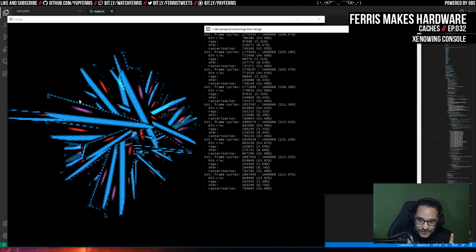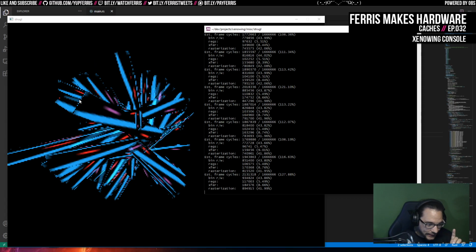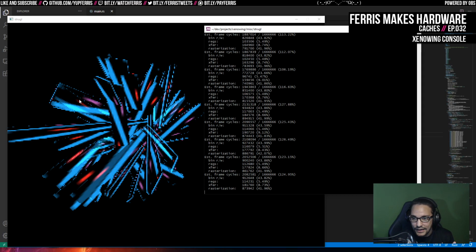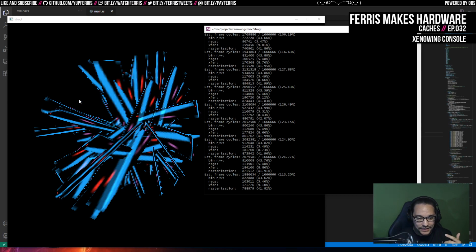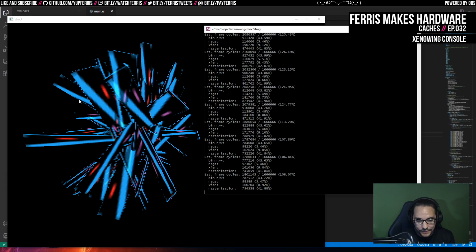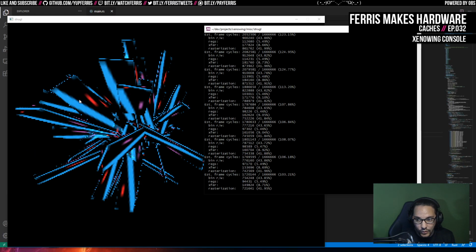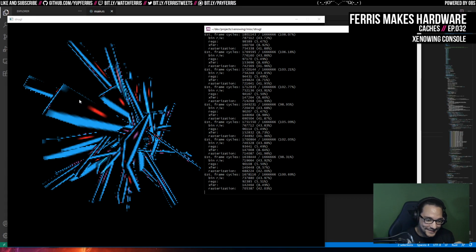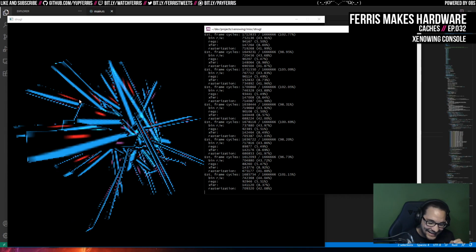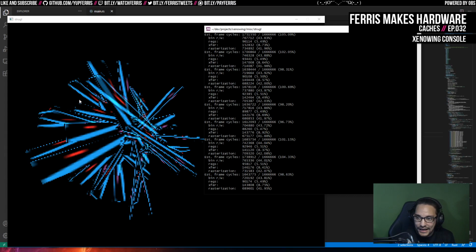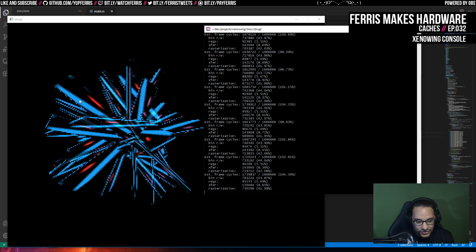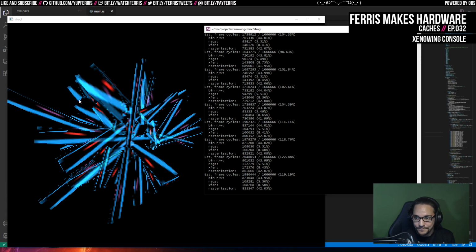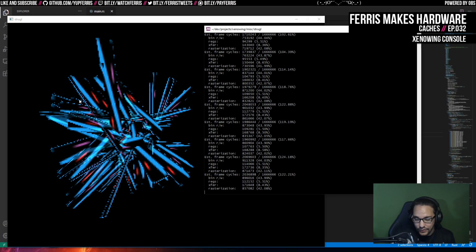And this was related to the texture cache when I think about it. This is kind of a problem because right now I have the texture cache set up so it only supports reading 1 pixel, one filtered texel per cycle. There it is. And there's a couple ways I can help with that. I think I can actually make it 2 without really any change because I think all the memories that I'm using for this are dual ported. So I think I can just use the other port on these memories.